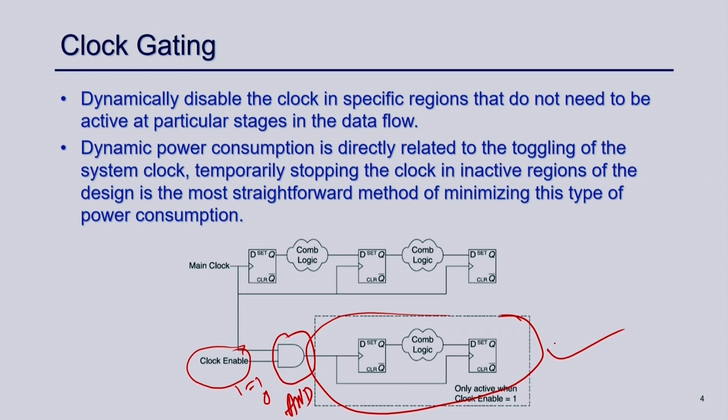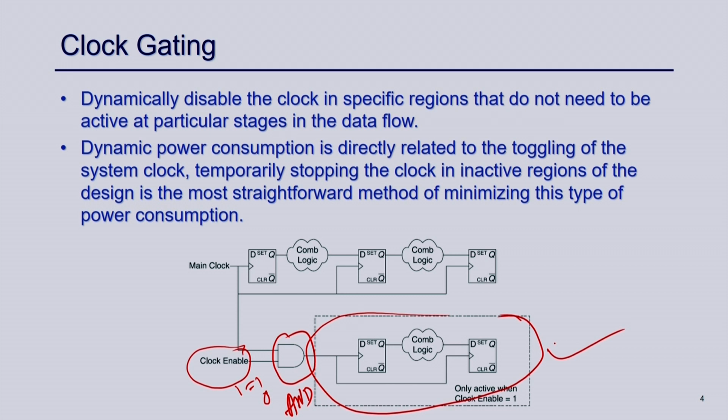So, this is what is called clock gating, and this is a very well known technique and is used widely specifically in the ASIC targets, not for FPGA, which we will discuss in detail. For FPGA this is not acceptable, or not a preferable power optimization technique. We should avoid clock gating if you really design something for FPGA. Okay. So, this is one technique that effectively tries to reduce the toggling, so effectively reducing the C, playing with the value C, right, which is capacitance.